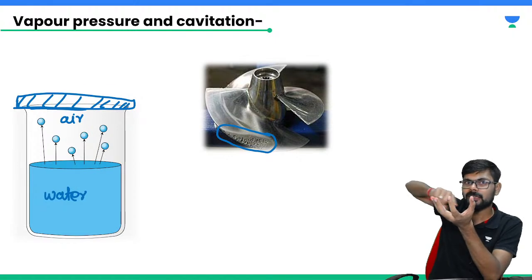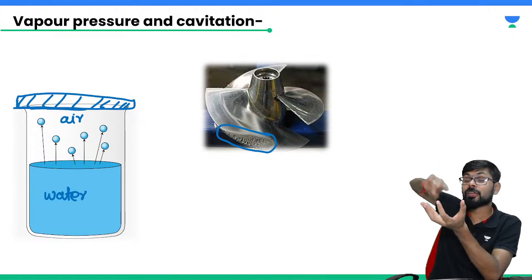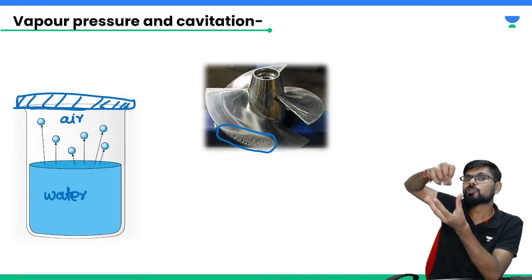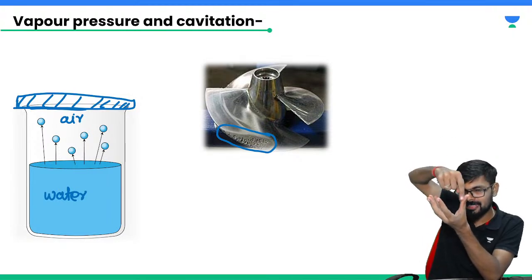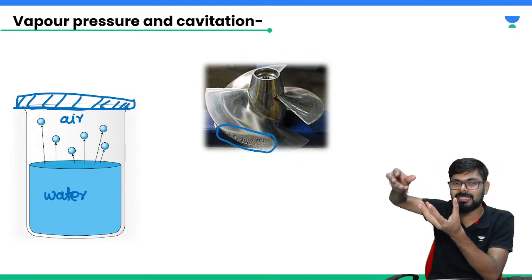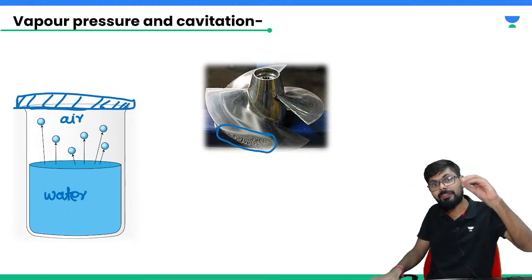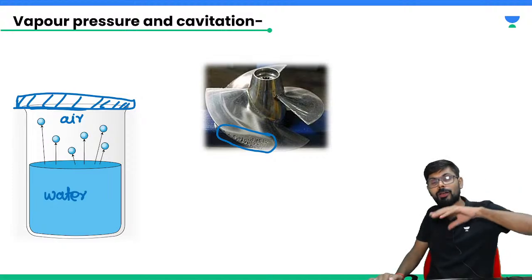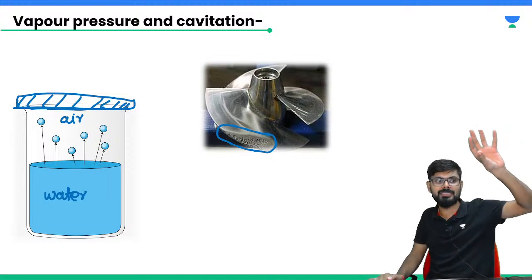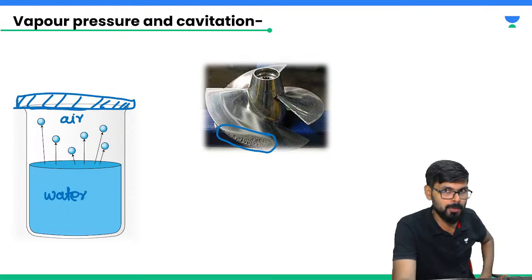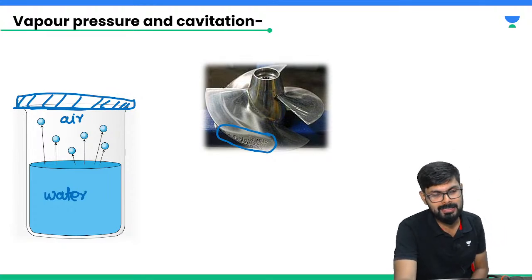This evaporation will take place, but the rate of evaporation will decrease. After some time this evaporation will stop, or we can say the air will reach the saturation condition. Whatever air is there inside will come to saturation condition or phase equilibrium condition. It means that after that, even though evaporation may take place, whatever number of molecules evaporate, the same number of molecules will rejoin the system.